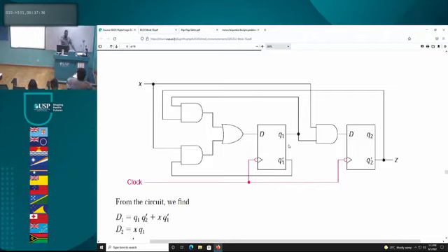Okay, so we did this yesterday. With this, we looked at this circuit. Firstly, how many flip-flops? 1, 2, 2 flip-flops. Each flip-flop stores 1 bit each. So therefore, this is a 2-bit system. That means at any point in time, it is storing 2 bits. The other point, this is a synchronous system. Why is it synchronous? Look at the clock lines. The clock lines are tied together, so they flip together. Every time there is a clock pulse, the system changes state together.